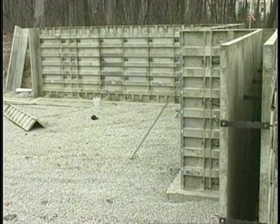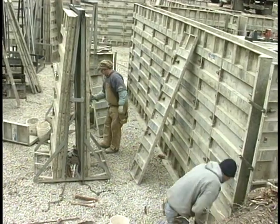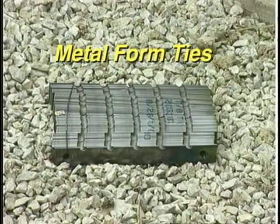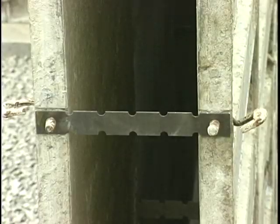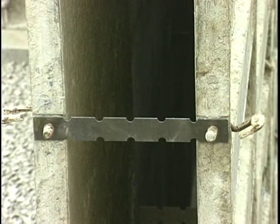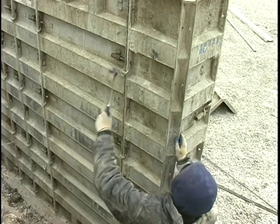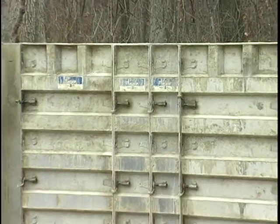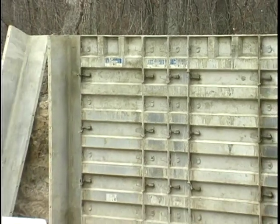Like a huge erector set, the correct size wall form must be used to come up with the needed wall shape, length, and height. As you build the form, place metal ties onto the form pins before installing the next wall section. After you fit one section of form against another, hammer the pins through and the locking levers down to tighten and secure the form.